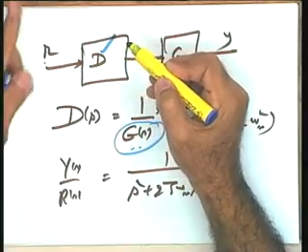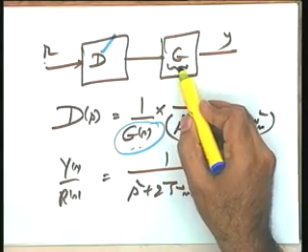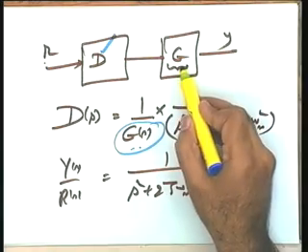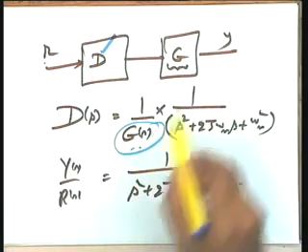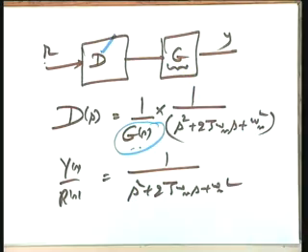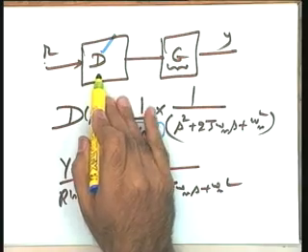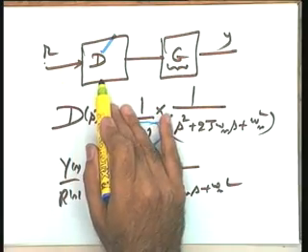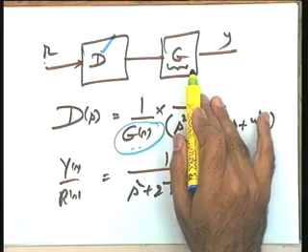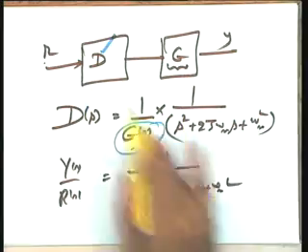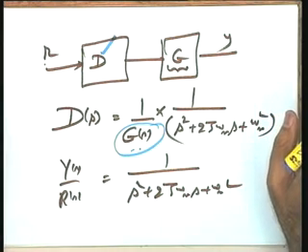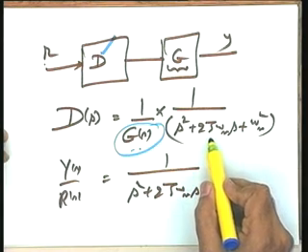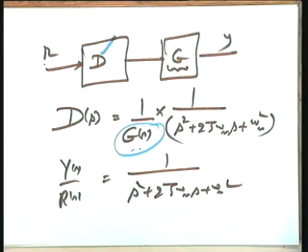Not only the modeling errors, this G you have used once for all. D you are not tuning online because the parameters of G may keep on changing with time. The G parameters in the model will not change because G is only a model. But the actual system parameters will keep on changing with time, and this change is not reflected in D. This D is not an adaptive controller which adapts to the changes in the G parameters, and therefore with time the performance of this D will deteriorate. It is because of these sensitivity or robustness requirements that you never go for this open loop solution, though it seems to be the most obvious solution possible.